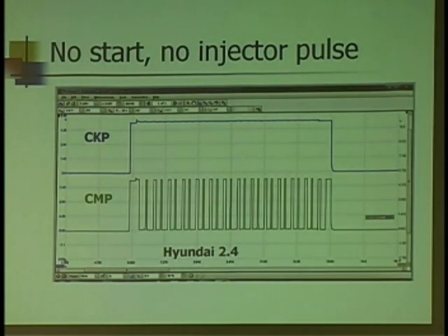And this is where I got in the no start. Well, I know for sure now I've got a problem with the crank sensor, right? I mean, it seems to be getting voltage, but I don't see anything being pulled to ground. I wonder, could I do a voltage drop test on that circuit with my scope? Am I doing a voltage drop test? What's the scope reference to? Reference to ground.